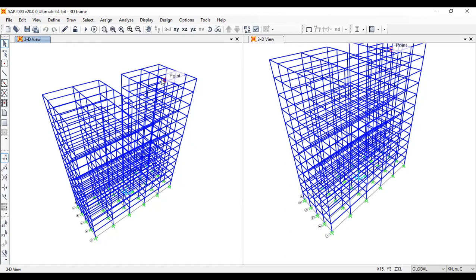But this kind of frame, you can't actually do it manually. That's why you need a computer analysis, right? From software. But if you localize a small frame and you know the loading, you can still check some results manually, whether this is giving the results we wanted. Sometimes you may have applied the same load twice mistakenly, and that's going to be a huge overdesign, right? That's why I always recommend you check a small thing. Even if you can check that the axial loads are correct, right?